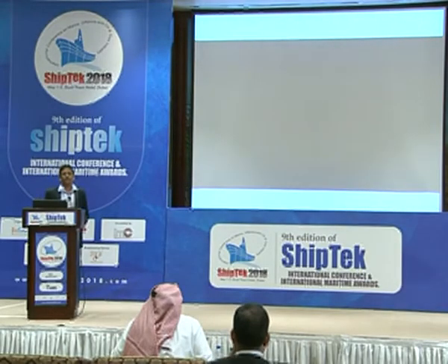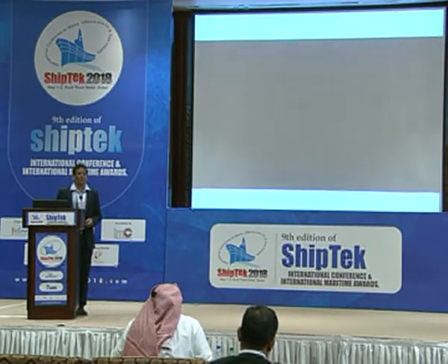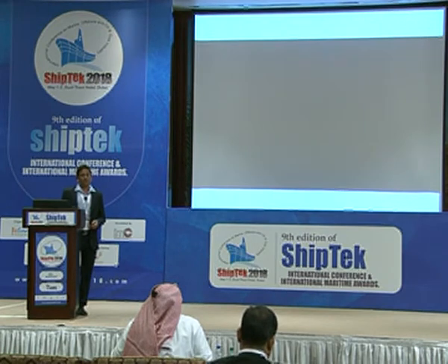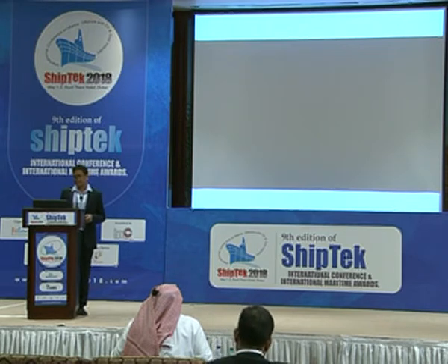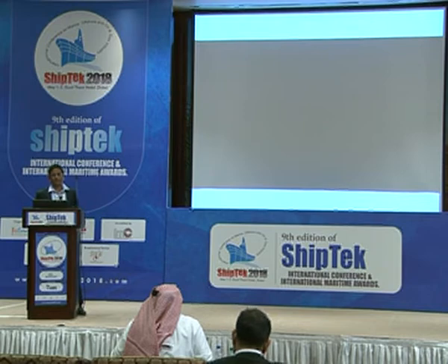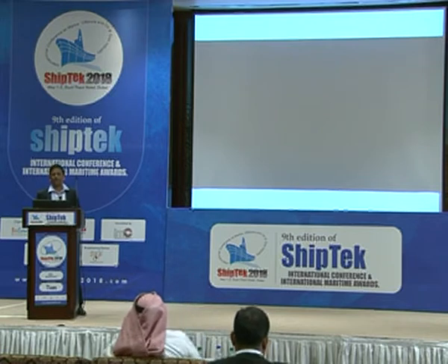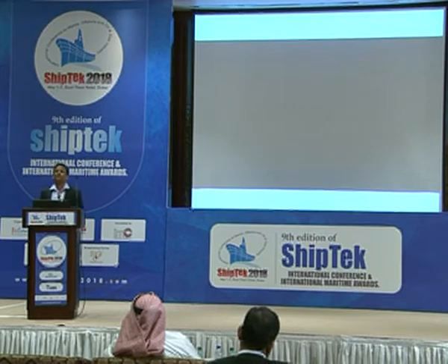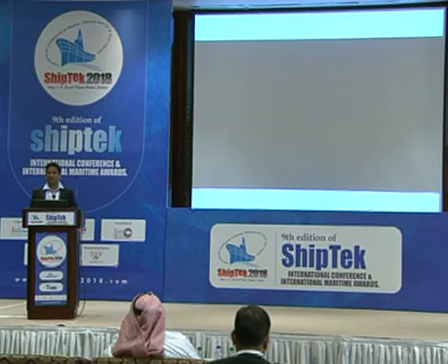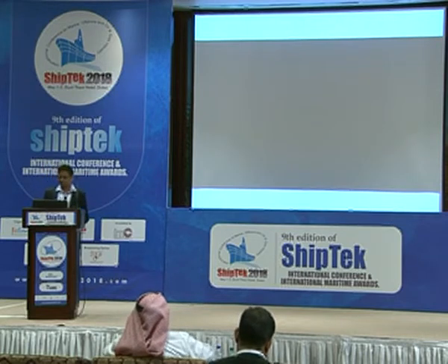Basically what we are trying to achieve is we will have a lot of sensors on the ships or offshore units, sensors for the motions, sensors for the waves, and we will analyze this sensor data and see whether an inspection is really required or not. As per today, we have a mandatory requirement, every 5 years you have to bring the ships into the dry dock, whether you have damage or not, whether the equipment needs maintenance or not. With the new technology, we will analyze the data in the office, and if it is really required, then you bring the ships into the dry dock.